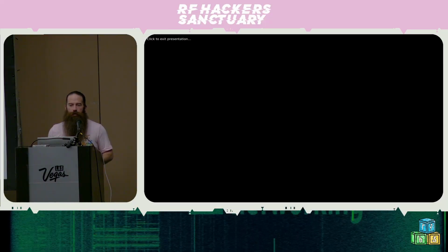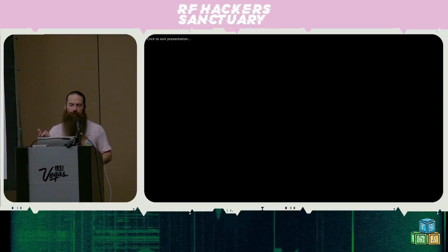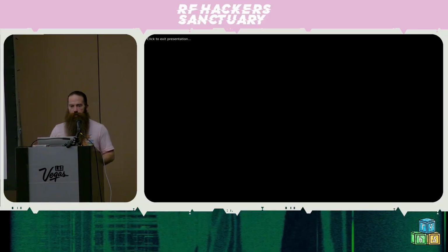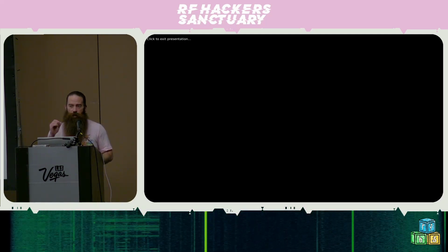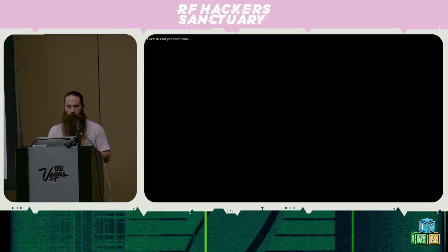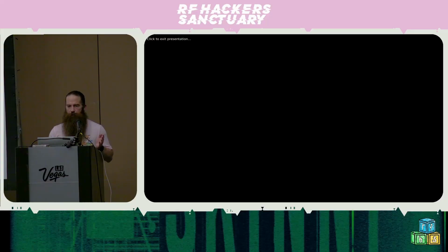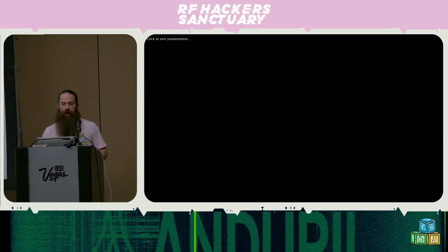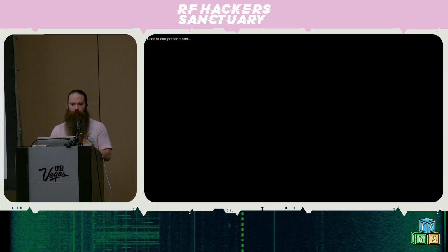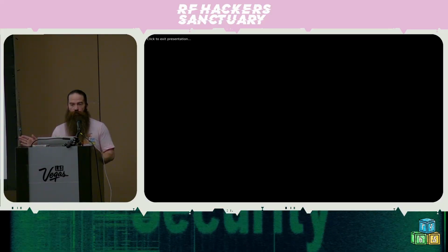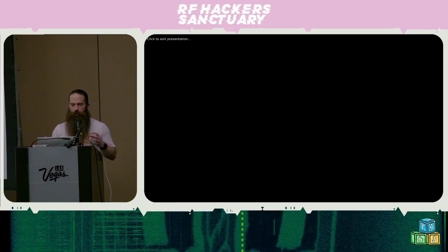So the flow graph is essentially the same. Instead of a BladeRF or a HackRF or an Osmocom sink, we're using a ZMQ sink. And then the examples that we have, the RF CTF files, are also on our GitHub. Those flow graphs are just the ZMQ source into a file or into an audio sink or something like that. Those are examples just to get folks started. But that is essentially what's happening on the other side. We have our own challenge runner that's running on the virtual side, specifically designed for the virtual things. And so there shouldn't be as much of a difference between the two.